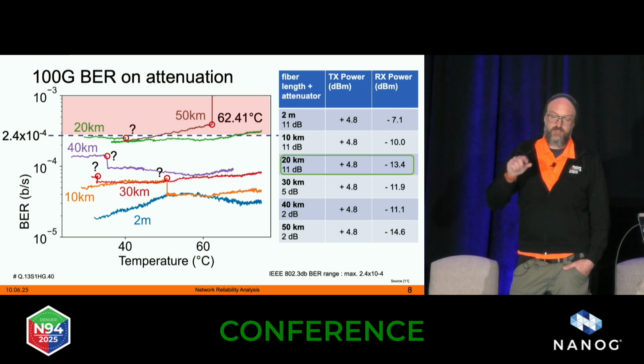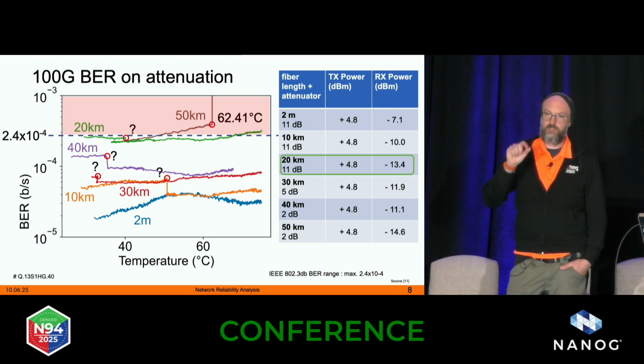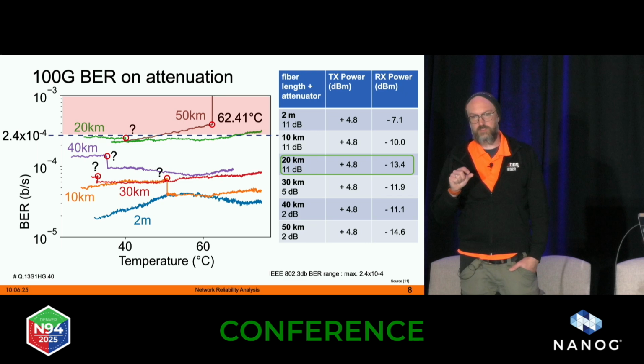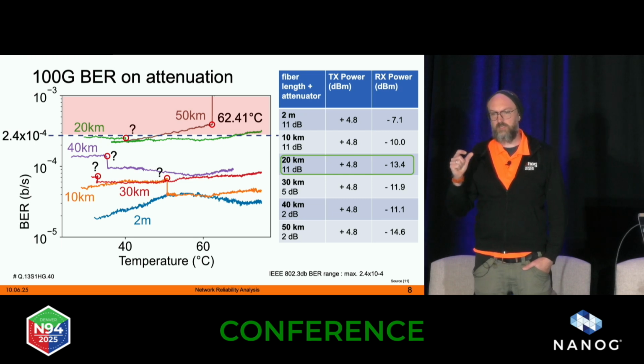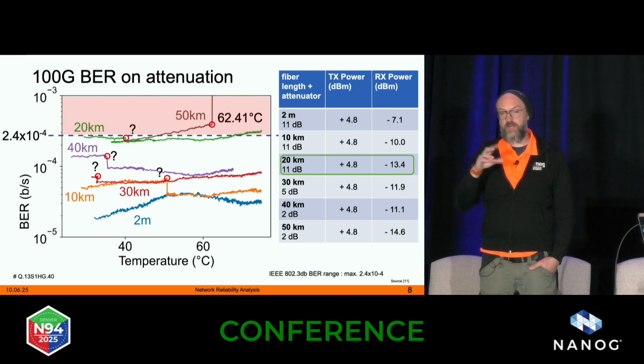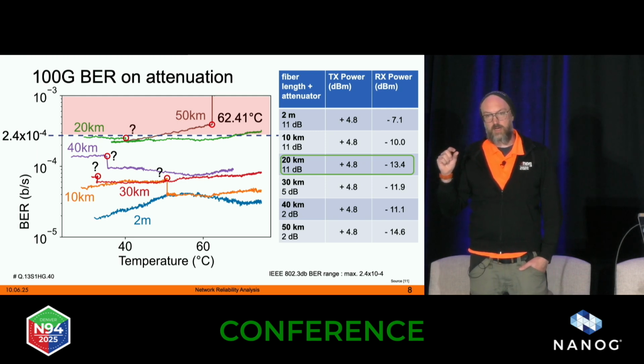Actually, this is a type of the implementation in the firmware of the transceiver's DSP. Depending on the temperature where we are, the DSP does a correction of the TX bias because we are looped. So the TX has a direct influence on the Rx. The TX bias is then corrected depending on the temperature where we are running.